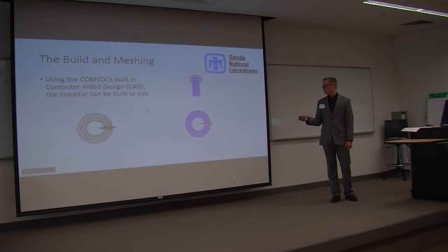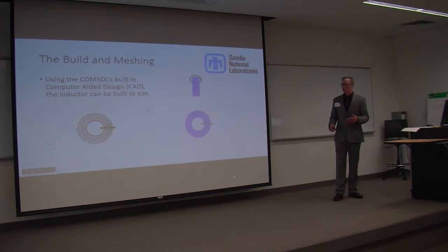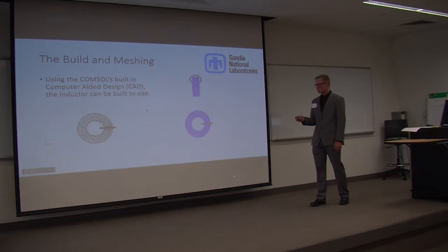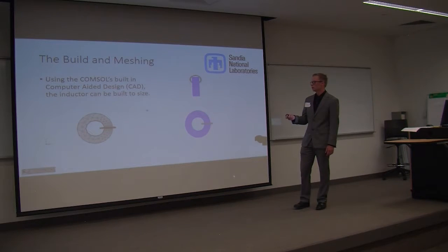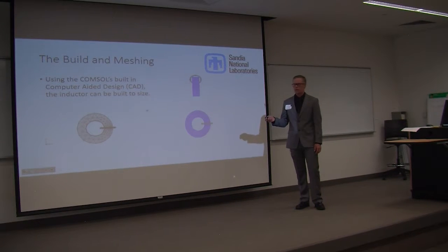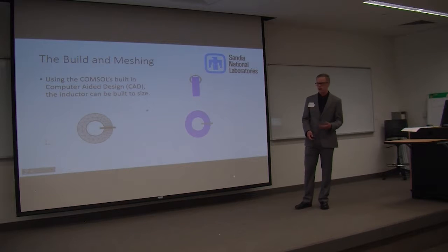The wiring we use here is 30 gauge copper wire, with a diameter of about 0.25 millimeters. The mesh I used varies depending on where I am. I use a triangular mesh, which gets smaller and is more focused on the areas of interest right around this coil, and gets gradually bigger on the outside where there's not as much going on and it doesn't need to be as scrutinized.